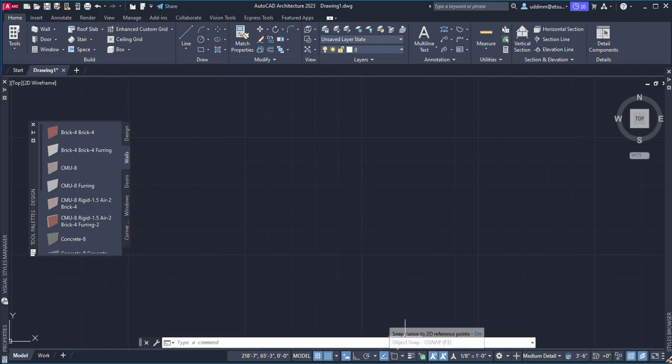But right now, if I move my mouse here in the middle of the screen and I just select F3, you can see that I have the ability to toggle the snapping on and off. So each one of the F keys will respond to a particular icon that's in AutoCAD. So as you work through AutoCAD, you will learn what those F keys respond to.